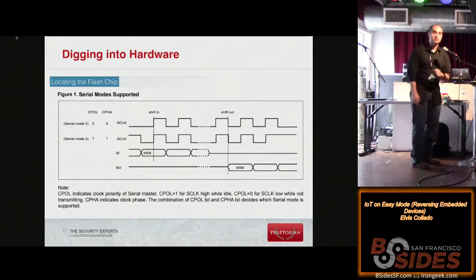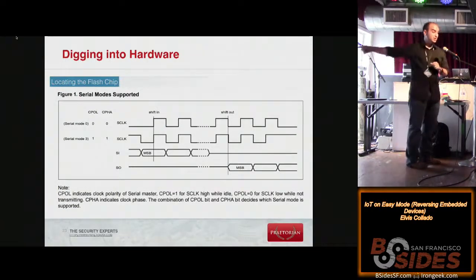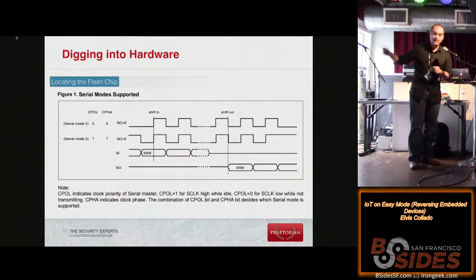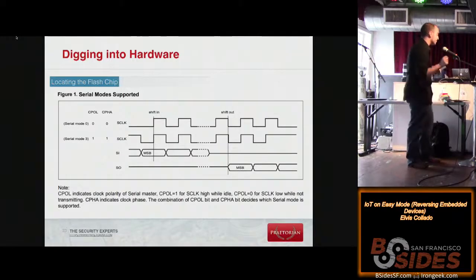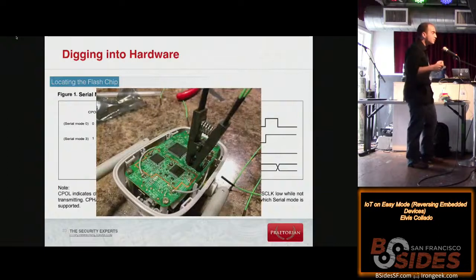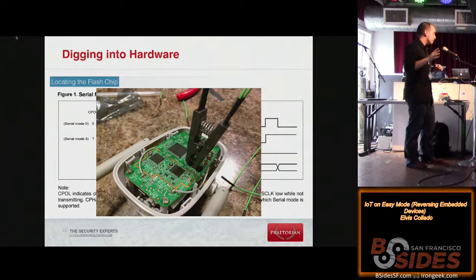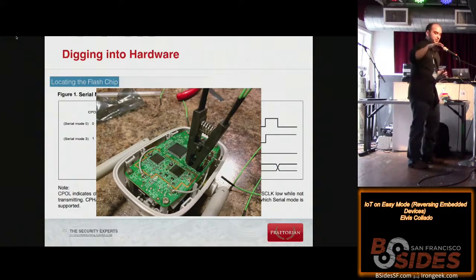We can also use our logic analyzer, so when we just hook it straight up and probe it, when the device is talking to it, we can verify that when there's a rising edge or anything else like that, it matches exactly this. So we can say, this is exactly the right data sheet, I know how to talk to it. We can pull it off, or we can use something called an SOIC, in this case 8 for 8 pins, probe thing, SOIC 8 clip, sorry, and we can just attach the leads off of it and do everything ourselves.